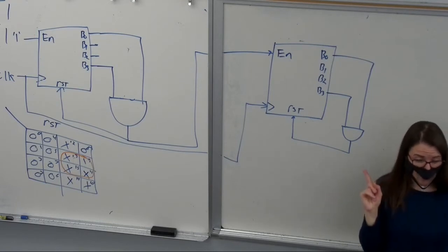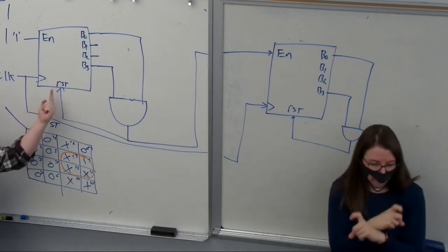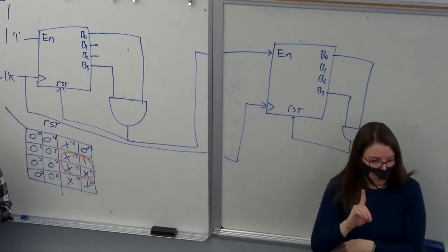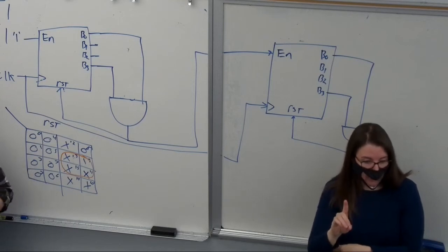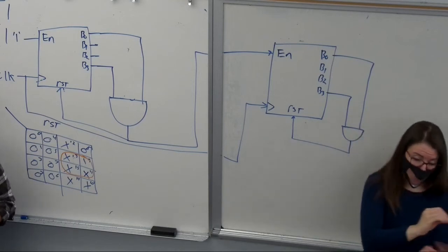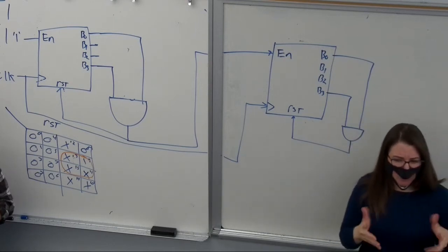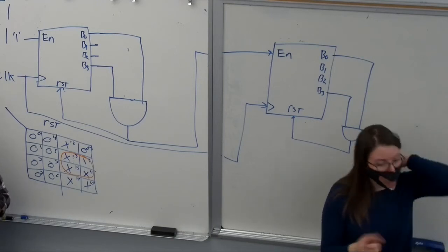And we can add an extra complication, like instead of reset, we could call it load, and we could give it a 4-bit load input. And instead of resetting from 9 back to 0, we could go from 9 to like 2, right? Because last time we talked about that parallel load circuit, I believe. Did we get there? Anyone? Or did I not get there yet?